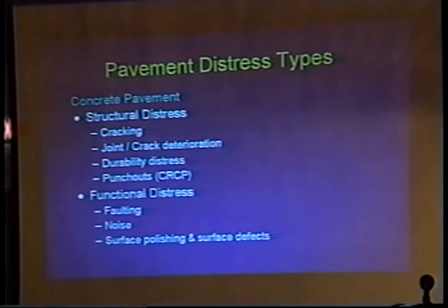Or if we did, we anticipated that the structural steel mesh would hold the cracks so tight together and would last forever that then we wouldn't have problems. But that's not the case. Steel under attack by water and salt will not last forever. That's why we're making a big push towards plain concrete pavements. Shorter joint spacing, 15-foot joint spacings, without the steel mesh. All it is reinforced with are heavy steel dowel bars at those plain joints.